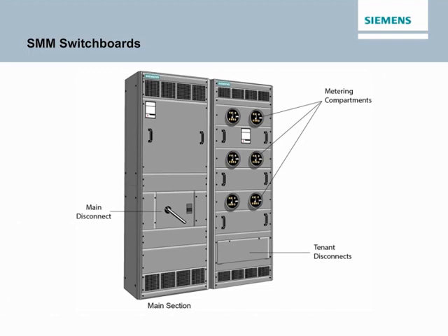wire. SMM switchboards have the following additional characteristics: UL listed and labeled, hot sequence metering standard, cold sequence optional, test blocks are standard, copper or aluminum bus available, 65,000 amp symmetrical bracing standard, higher bracing is available, type NEMA 1 or 3R enclosure, it meets UL 891 and NEMA PB2 standards, and ring type meter cover design.